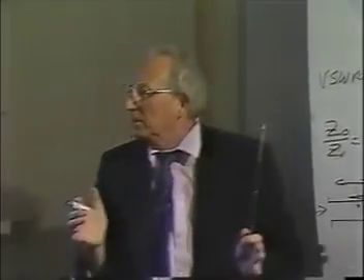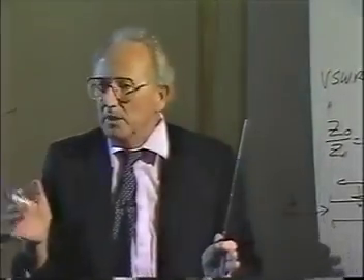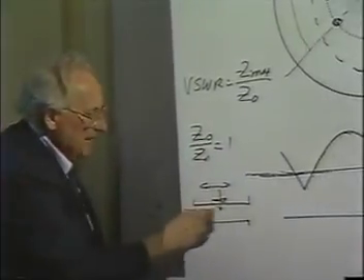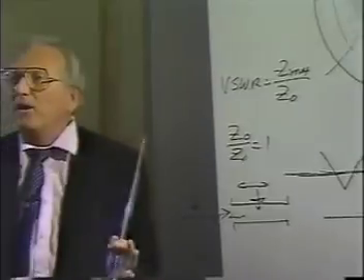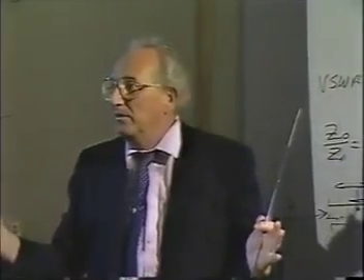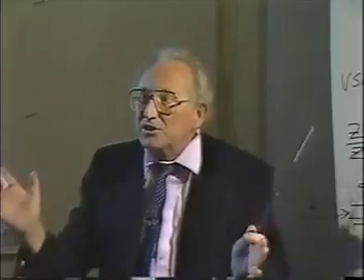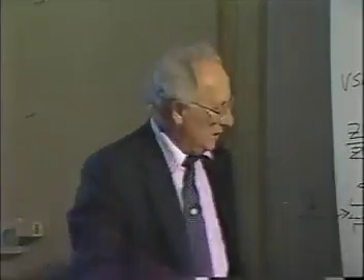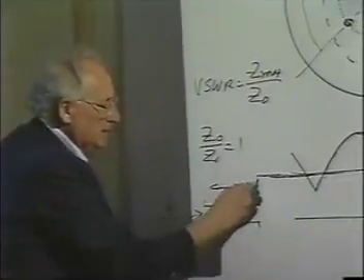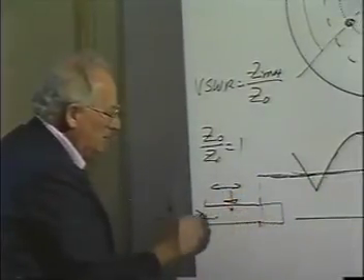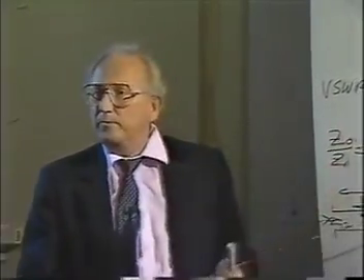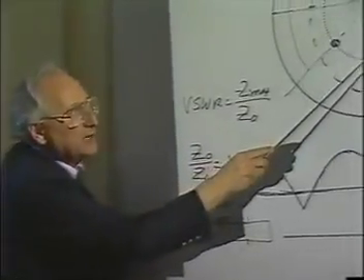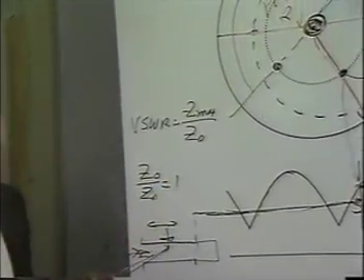That's how you actually match. We'll do that here in the classroom later, a few lectures from now, because we're going to put a system up and you'll get a chance to try your luck at this. If I move this back and forth until I don't see any wave coming back out of here, I see no power coming back. That means I have no standing wave. Right? I match the transmission line. If I took this away now, disconnected here and put a perfect load on here and measured the VSWR in here, what do you think I would see for this problem here? Well, in order to cancel this 3 to 1 mismatch, you have to put a 3 to 1 mismatch in here.